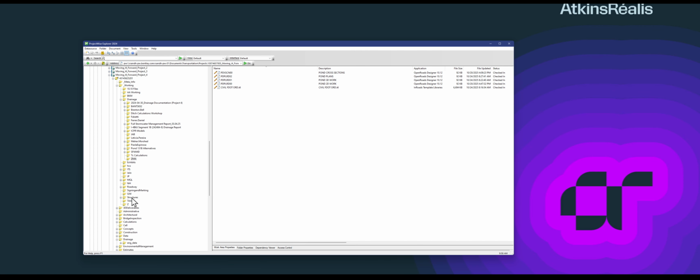So as for us here, unfortunately, again, they don't care for drainage, like I said. And also, if the project-wide admins were doing their job right, usually in roadway, they drop the ITL library file there. So the roadway people come, and how FDOT wanted it is you type your project FPID number here, .itl, and that's for your project. But if you have different libraries like we did in this big project, you can do that, a bunch of libraries for the main line, the ramps, whatever.